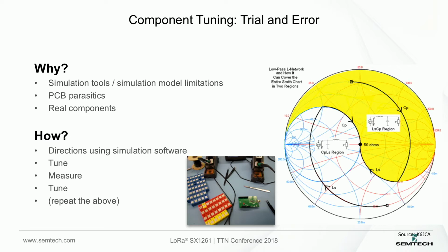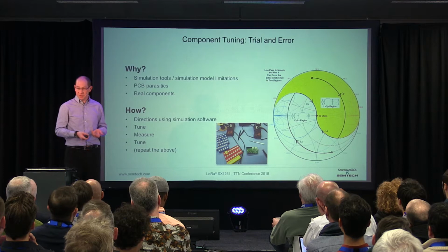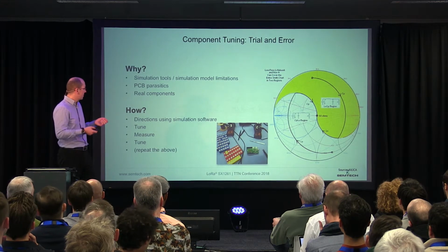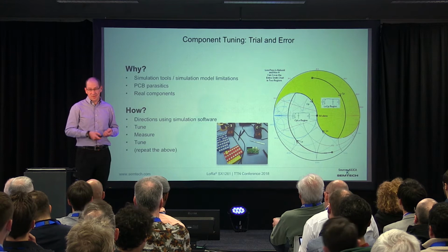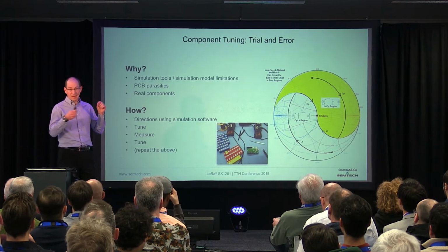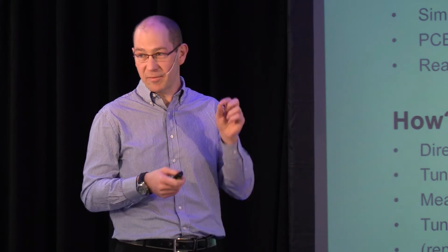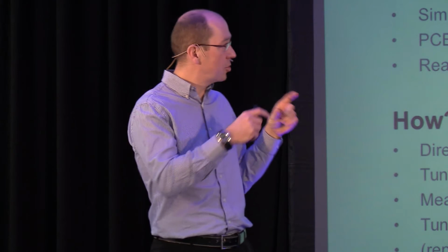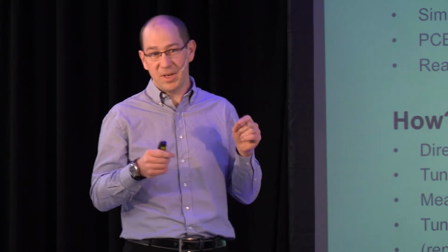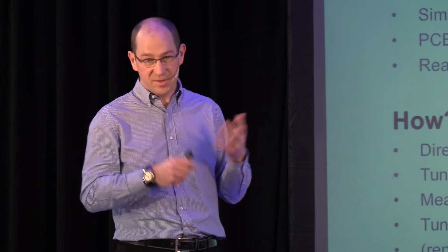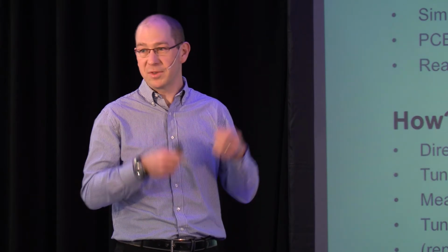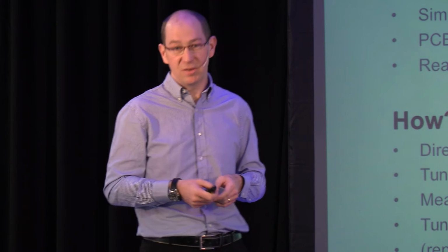But why do we have to fine-tune? I mean, we have simulation software for that. It's not as when I was in school, where we had to draw on the Smith chart and so on. Now we have very good tools, but why do we have to tune afterwards? Because every software has limitations. Very basic software have, let's say, large limitations. There are very powerful software that are very precise. If you have a good model of your PCB and of components, you can be very close to your target, but this requires a lot of time to play with the tool and have the right simulation bench in place.